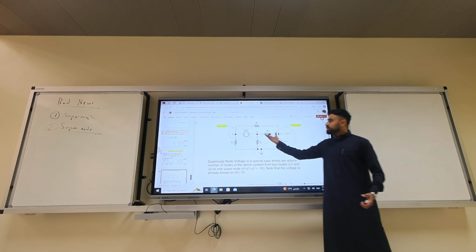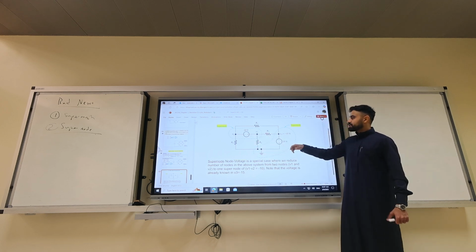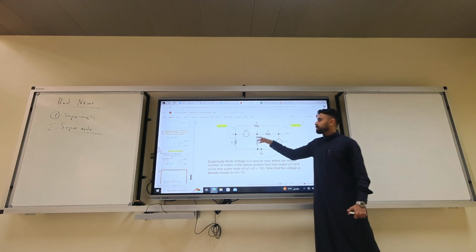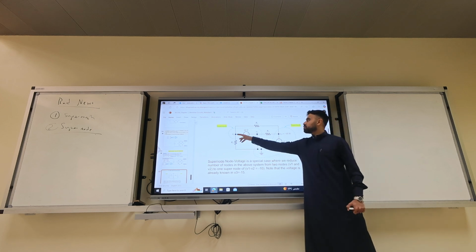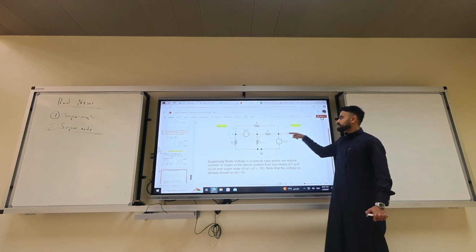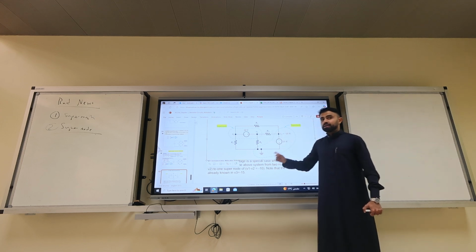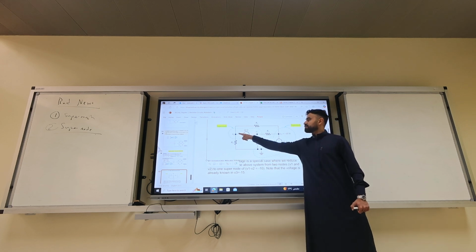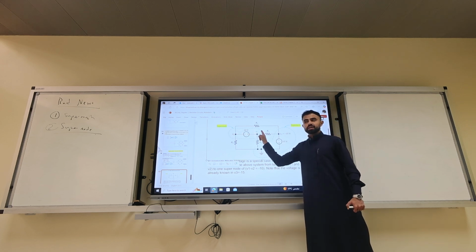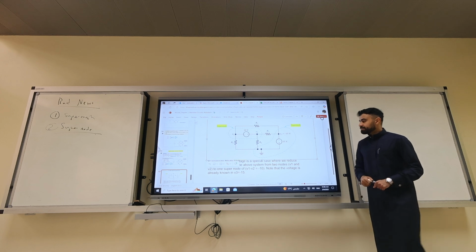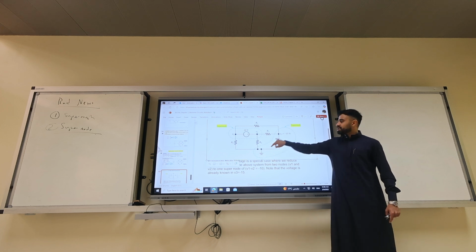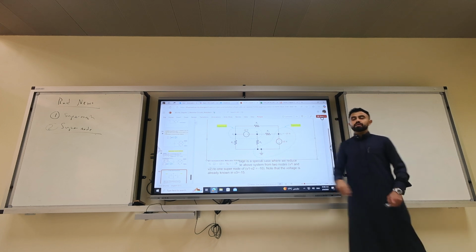Right now, you have a giant supernode where you have the voltages to be, you write the equations. For example, you call it V minus 0 over R2 plus V minus R1 plus V minus V3, and then at the end you add V1 minus V2 equal to minus 10, because V1 at the negative, V2 at the positive. Okay? Let me re-explain it again. It is already known that V3 is minus 15 volts, because the battery is minus and plus 15.